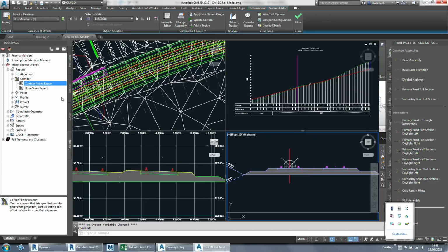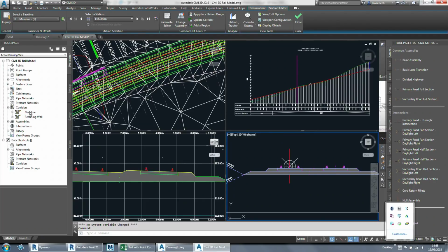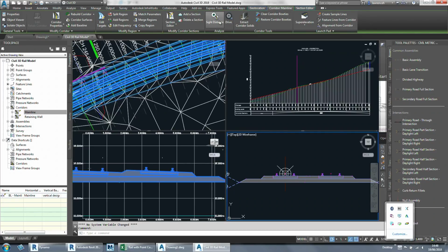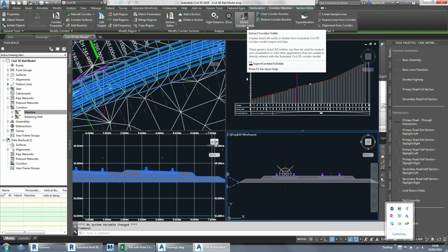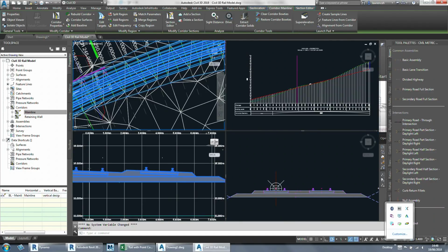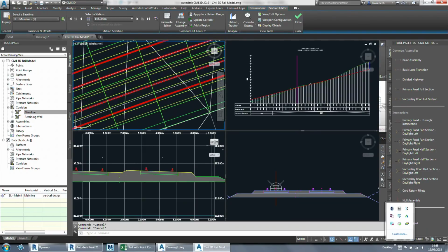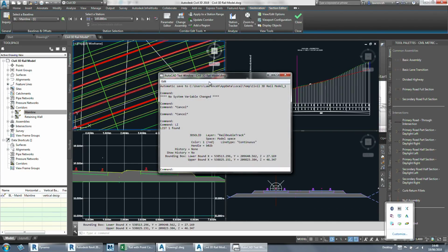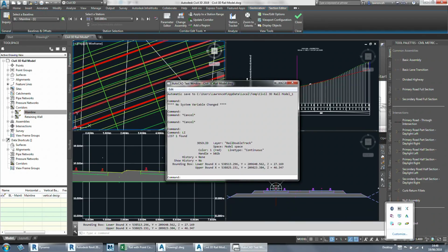Okay, so moving on from that, if we go back into Civil 3D here, one of the most important things for this is to make sure that you get the corridor out and the corridor solids out first. So what I'm going to do is just go ahead and select the corridor in here. Not sure if you're aware of this, but in Civil 3D, you can extract those corridor solids out as physical solid bodies. And like I say, when I actually do this, Civil 3D will take out all of the solids, as you can see here. So there's one solid. If I just list that, you can see that's a 3D solid. When we extract that out, not only are we taking out the solids, but we're taking out that green circle, which gives me that datum, that local datum inside Revit.